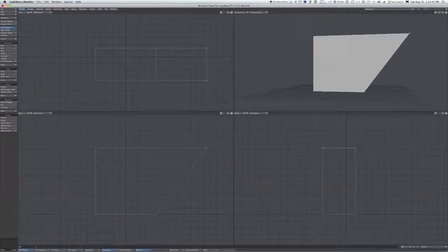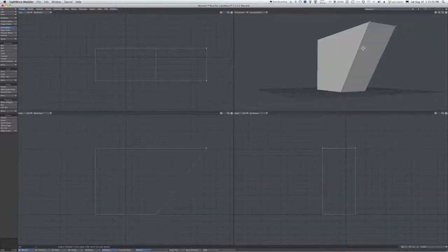That being said, this edge up here may have some little blemishes on it that you have to clean off, either with a little sandpaper, a little file, or a knife, because when it comes over, it's going to print a little bit further than the last layer. So there may be a little blip, a little wart.